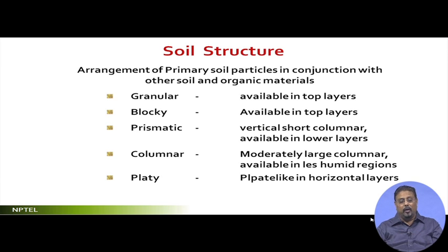Now, as per technical literature, there are different descriptions of the structure. One is granular. There may even be fine granular. Granular means we have granules which are holding to each other, which are quite significantly large in size or of differential sizes. Generally this is the layer which we find in the top layer of the standard good earth or good soil. There can even be fine granular. That means you have the granular, but the particle sizes are very, very small. So, if you hold it, it almost comes out like a sort of dust. That is also possible. I am not going into that detail of it.